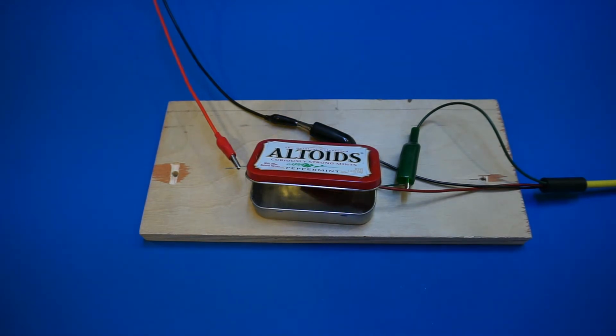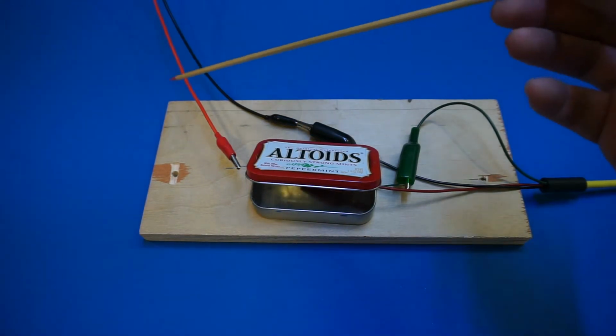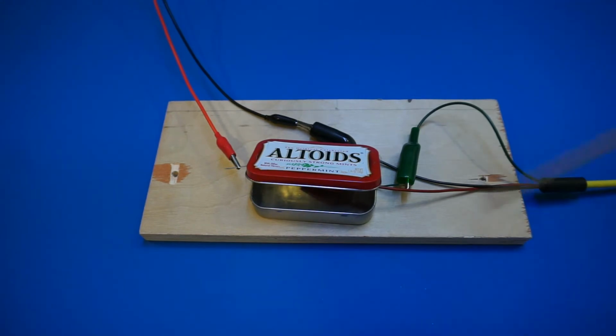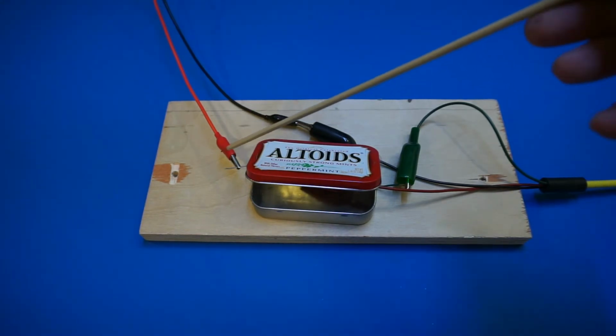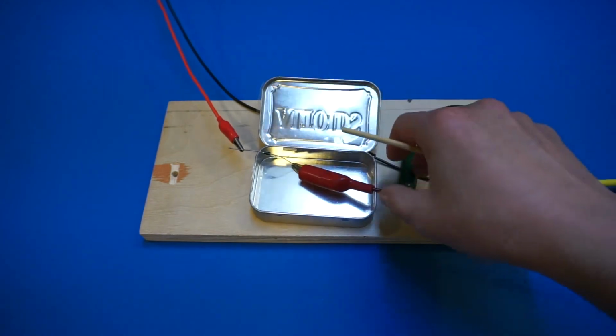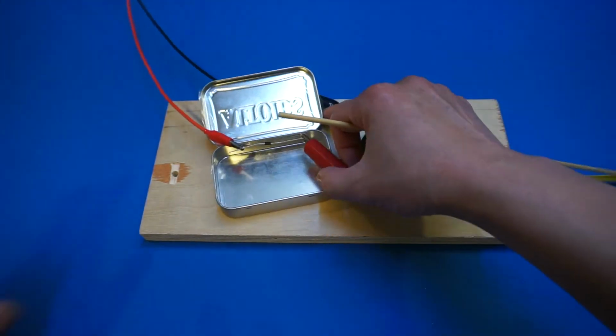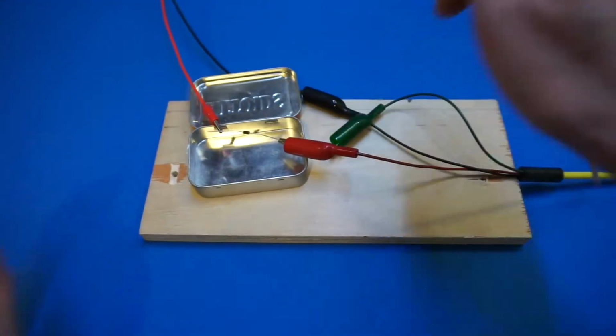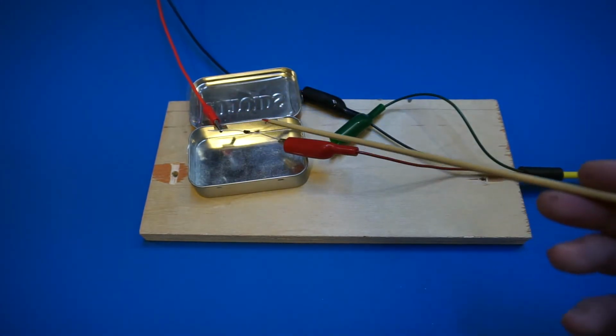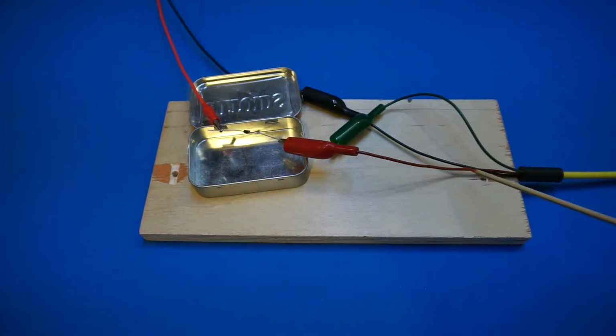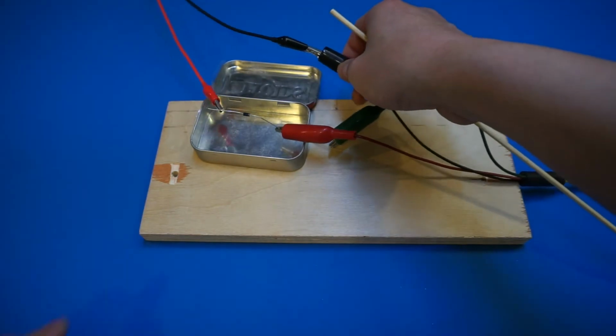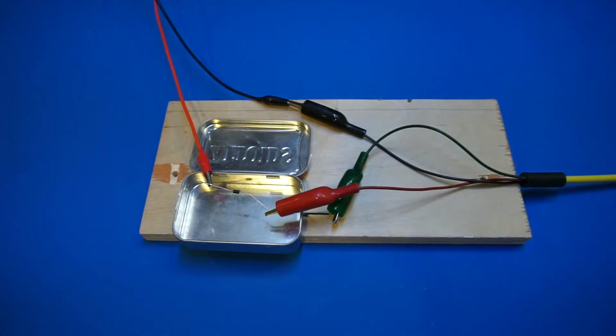So let me briefly describe the setup. Here from the left you can see the leads coming in from the voltage standard, and the positive is hooked up to the positive of the diode, and the negative goes through the positive input into the electrometer to measure the current. And the electrometer's terminal comes back here. This is the negative, and I connect it directly to the voltage standard, so it forms the closed circuit.